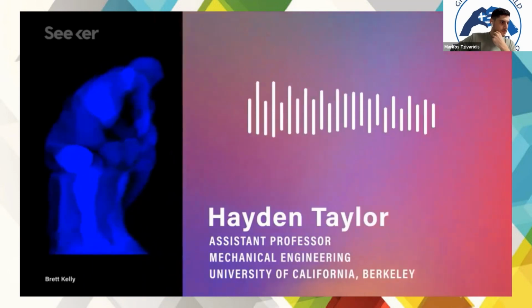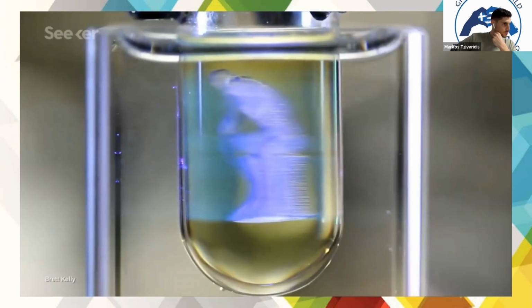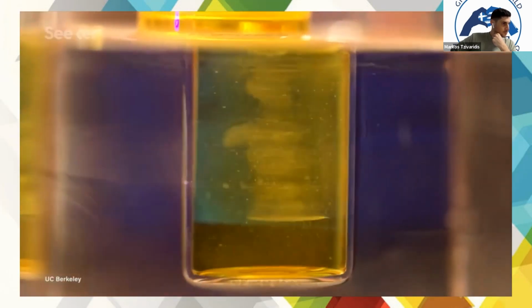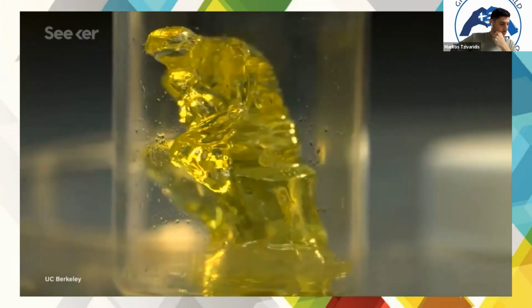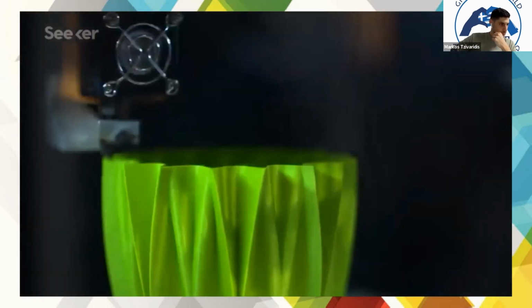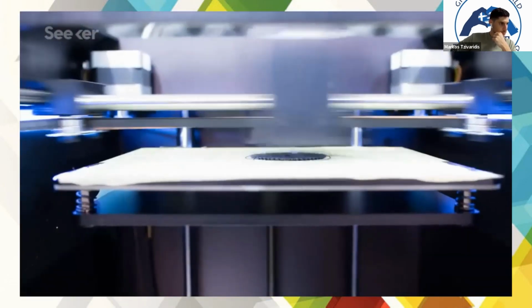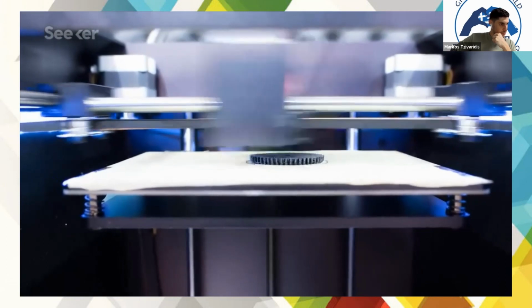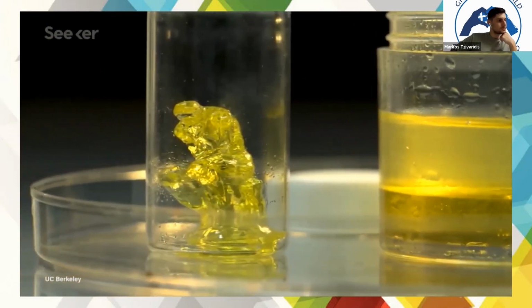Volumetric printing is a category of additive manufacturing where all points inside a 3D object are materialized or created pretty much simultaneously, as opposed to building up the geometry layer by layer, which is how virtually every other existing additive manufacturing process works today. So CAL is printing smooth, complex geometries like those found in the statue The Thinker. There are no symmetrical sides and no hard staircase-looking edges, which is totally novel.